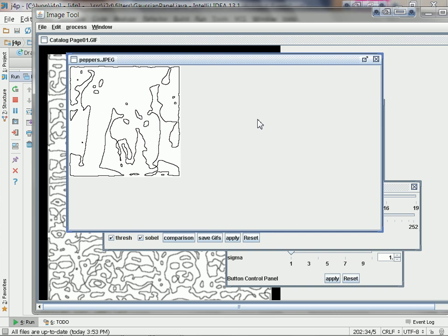Raster to vector conversion is just the first step, however, because if you have a series of vectors that are not connected, then your laser will take forever to do its cutting. So your post-process to the raster to vector conversion includes vector ordering. Now, vector ordering is interesting because it's NP complete. And what that means is it's as hard as any problem in NP space.